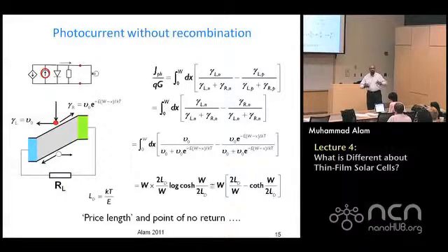And eventually there may be a point, as I will show in the next slide, where this is flat, half going to the wrong contact, half going to the right contact, and essentially you have zero current. Voltage independence cannot hold in this particular case, right? It's simple. Why it is voltage independent requires a lot of discussion, but why it's voltage dependent should be simple to understand.